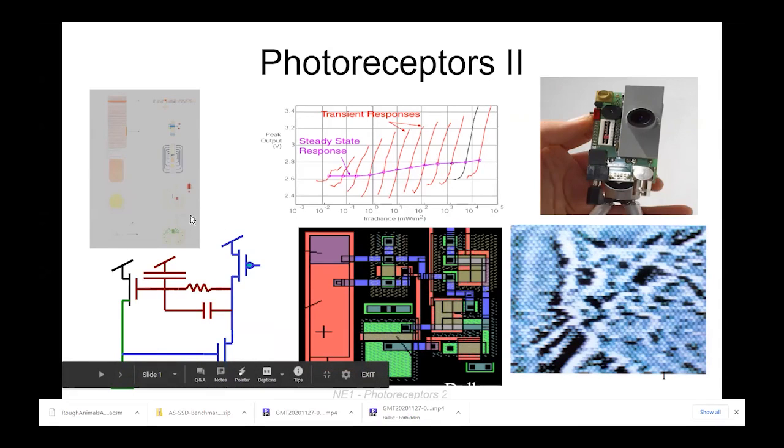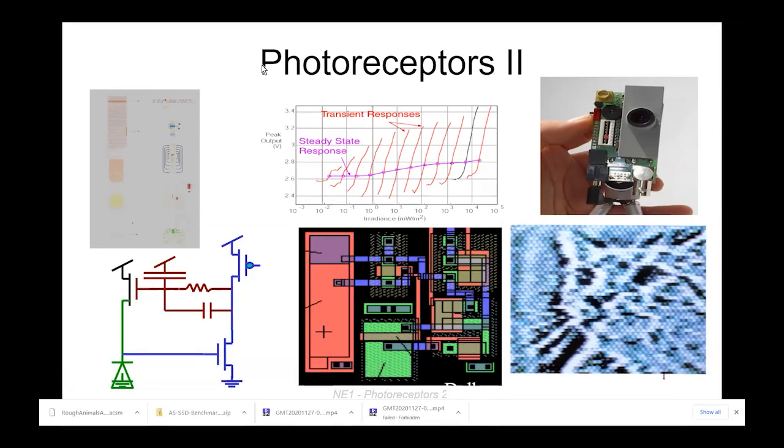And in the past, we always taught about this adaptive photoreceptor. Does this circuit look kind of familiar to you? It's the same as the circuit you tested, except for that red part right here, right? And what I'll try to explain to you in the context of the circuit that you tested so far is that this red part here acts like a kind of a feedback circuit, which has decreased feedback at high frequency.